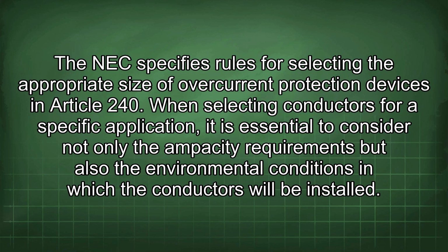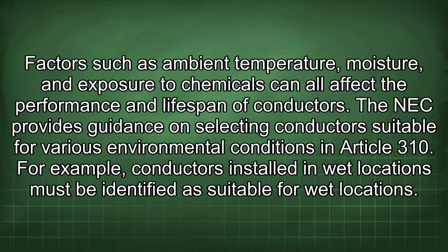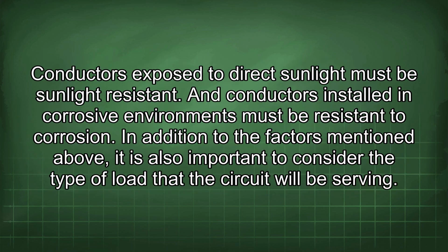When selecting conductors for a specific application, it is essential to consider not only the ampacity requirements but also the environmental conditions in which the conductors will be installed. Factors such as ambient temperature, moisture, and exposure to chemicals can all affect the performance and lifespan of conductors. The NEC provides guidance on selecting conductors suitable for various environmental conditions in Article 310. For example, conductors installed in wet locations must be identified as suitable for wet locations. Conductors exposed to direct sunlight must be sunlight resistant, and conductors installed in corrosive environments must be resistant to corrosion.